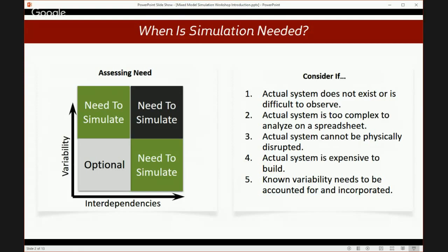It was just 5 sequential workstations. And as we teach you in class, you balance on paper, and then at the end, you balance when live. And that's what we did. We went straight to bringing it live and balancing it right there when it was live. But what you have to consider is an intermediate step between balancing on paper and balancing when live, and that is balancing with a simulation model. The more interdependencies, products, processes, the more variability, you have to consider simulation as a must.